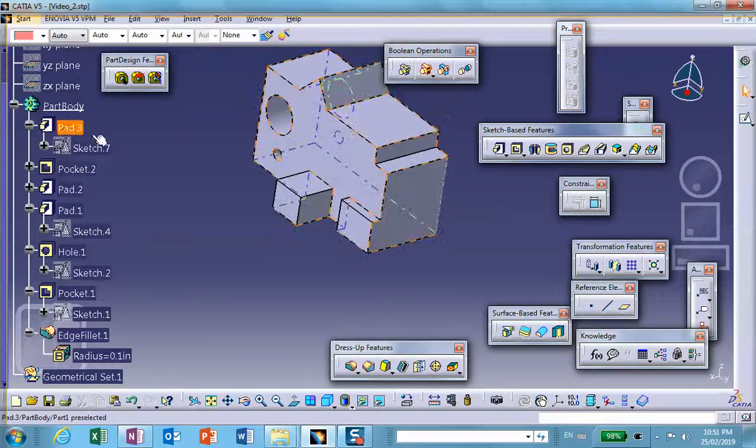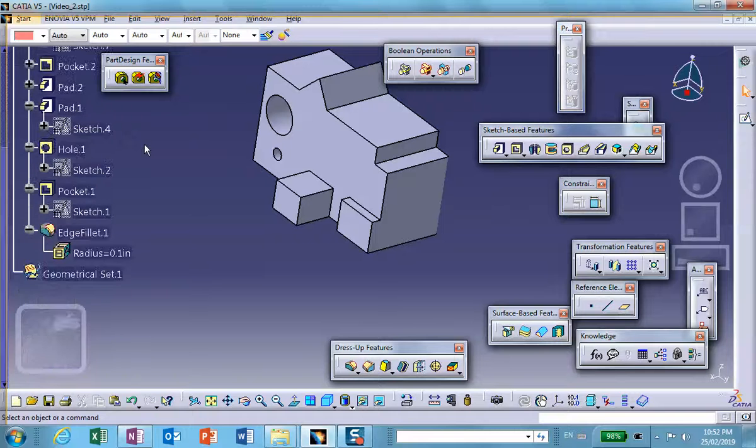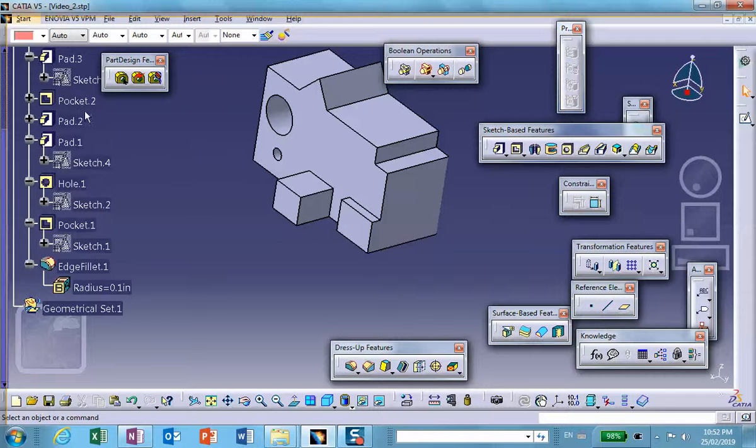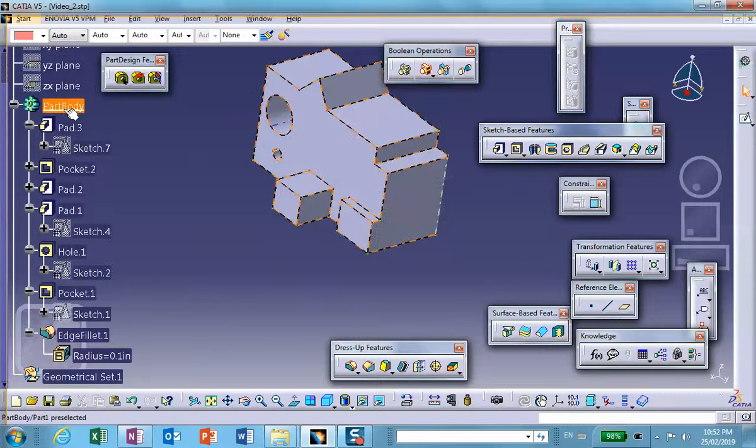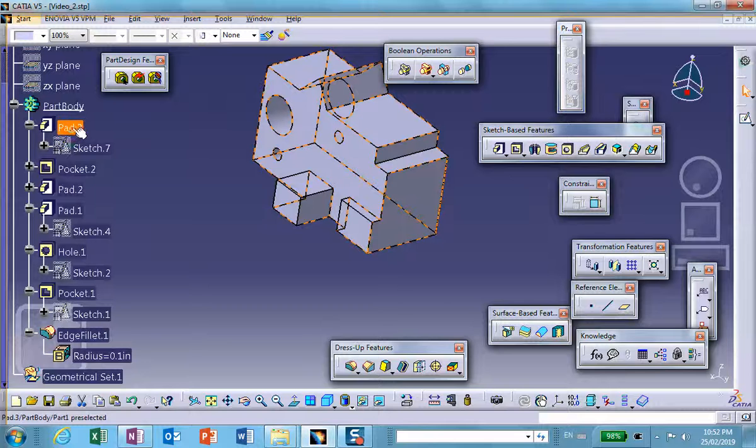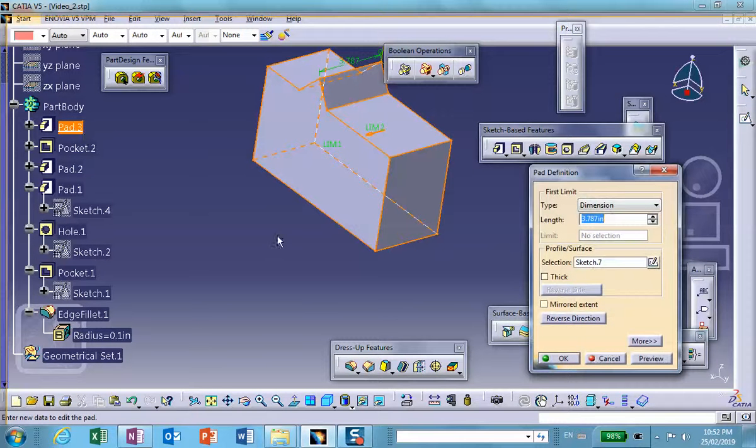When I extracted it, it got rid of that dump solid base, and everything is parameterized now. If I go to this path, of course I can't delete that because all these other things depend on that. No wonder I couldn't delete it. But I can make this thing, for example, let's make this thing 6 inches. There we are.